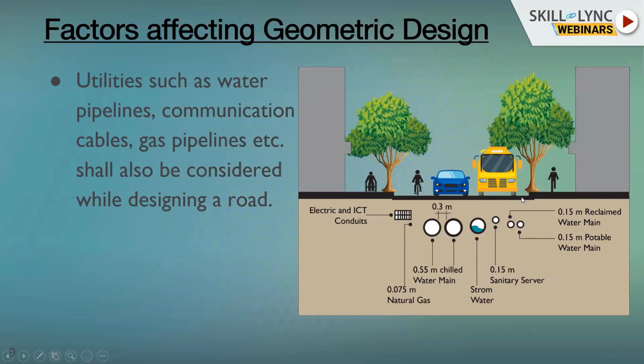You might have observed there will be a steel grill on the road, right? So these are the catch basins. When a water droplet falls on the road, the water should go into the catch basin. In this road, the catch basin must be somewhere here, and they'll have a pipe, and they'll connect to the stormwater, and this stormwater may connect to the nearby streams or wherever they want, or the ponds.